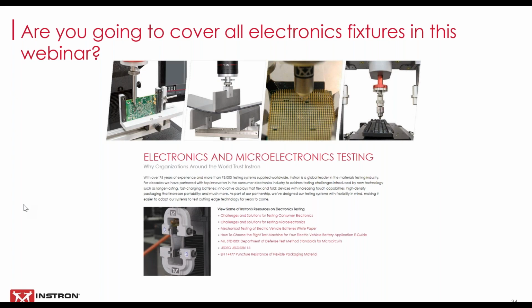For example, for the power supply, you might go in and calibrate it. When there's no button being pressed, you would expect there to be 0 volts. So you would do a coarse calibration there, and then you would press the button down and input into the software that that would be associated with 10 volts.